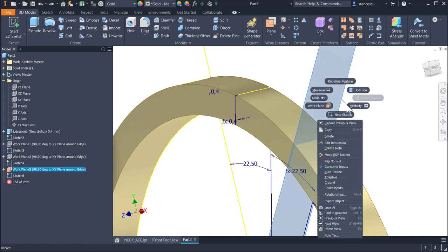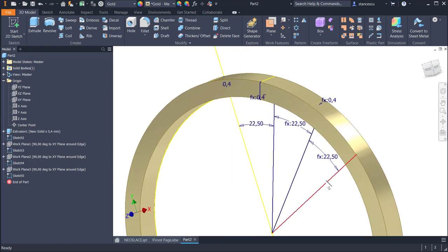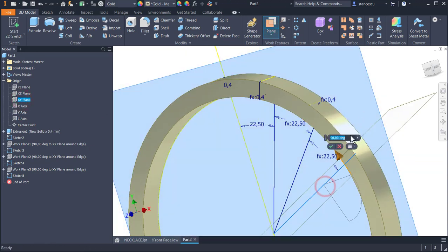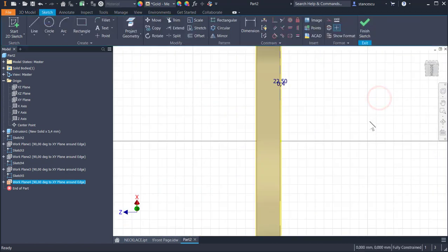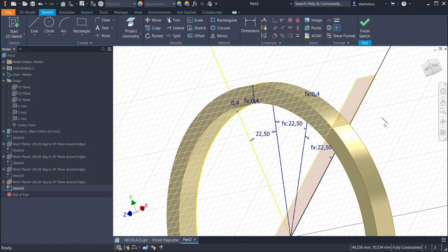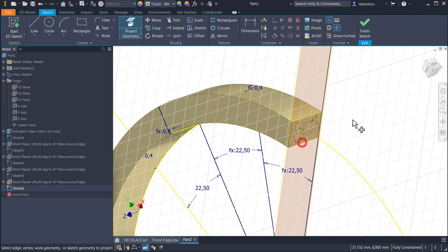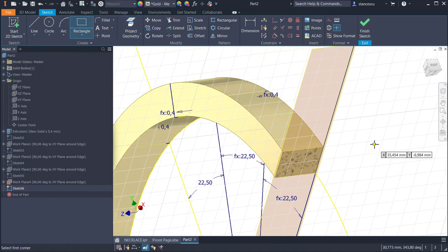Finish sketch, visibility, next and last line is this one. Plane, XY line, OK, sketch. F5, F7, we project again. We can select here construction projection, and we have construction line, but now we have to deselect, to unselect this, because we draw the last rectangle.